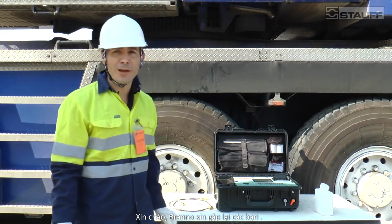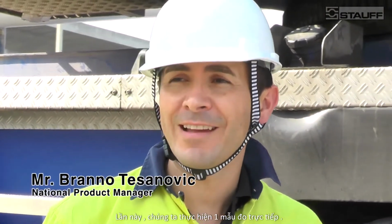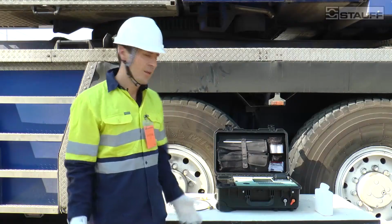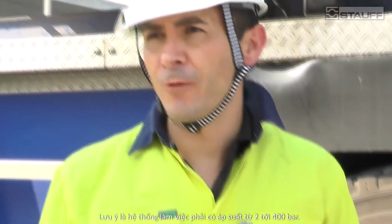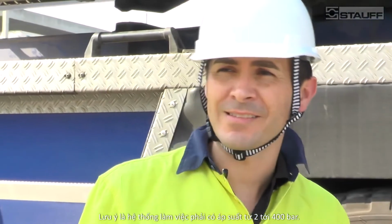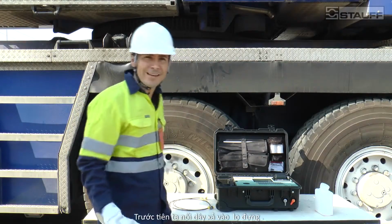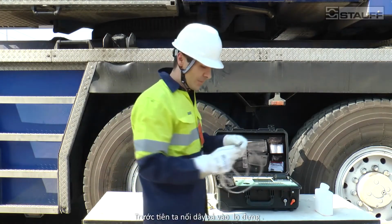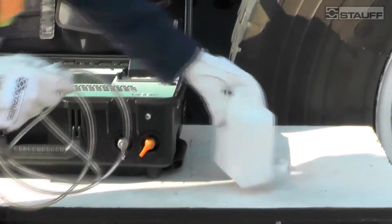Yeah, hi, it's Brenno from A-STAUFF Corporation again. This time we're going to perform an online test. So in this case, the bottle sample is not required. We can connect our particle counter directly to the system. Just ensure before you connect that you have no more than 400 bar of pressure in the system or no less than 2 bar. So the first thing is to connect the waste hose into the waste bottle.